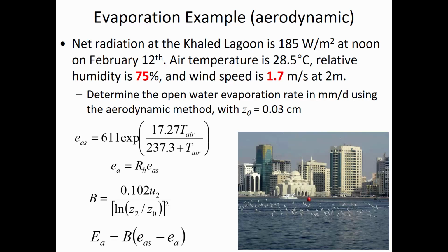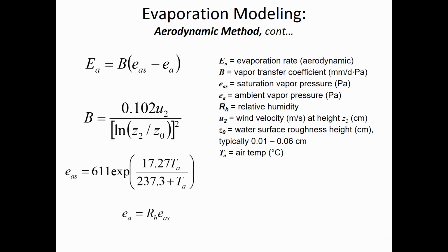All right, so if anybody else also did these calculations, do you get 0.002237? All right, good, thank you. And the units there are millimeters per day Pascal. So 0.002237 millimeters per day Pascal. That's called the vapor transfer coefficient.